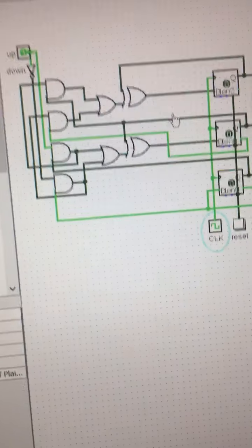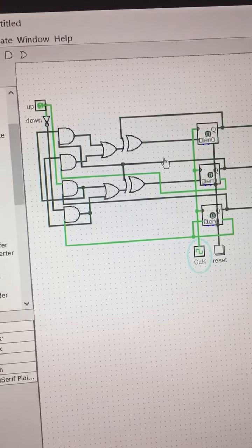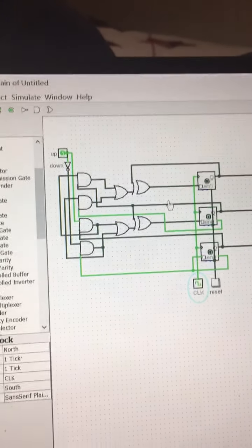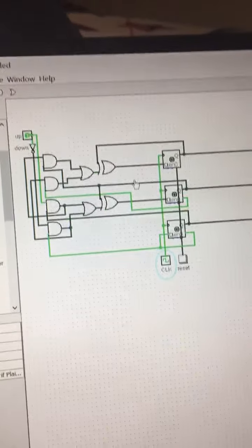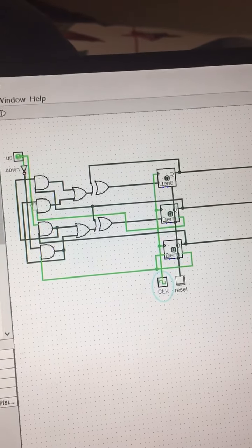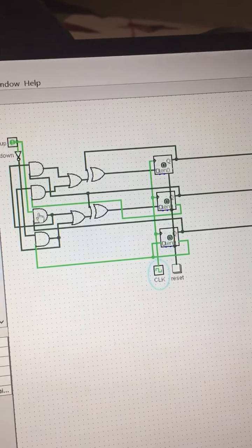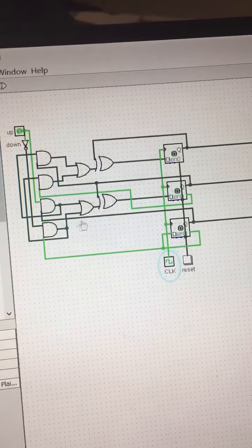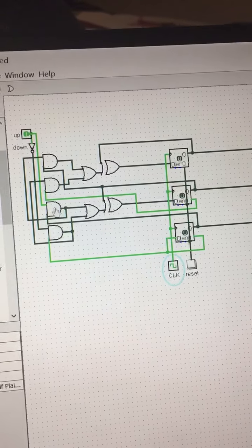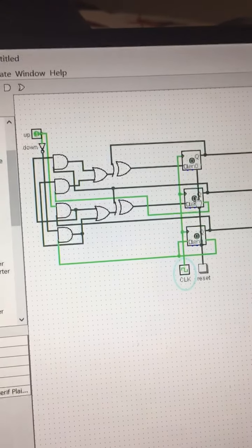What about the rest of the digits? Well, if you really think about it, when does a digit change? It checks the previous digit. It checks if the previous digit has a carry or does it borrow one. So basically, if it is an up count, which goes to here, and then if it also has an output of 1, right? If we AND these two, then that means it has a carry. So we have to change the current digit, which is the second digit.